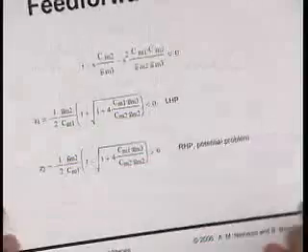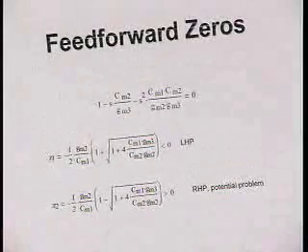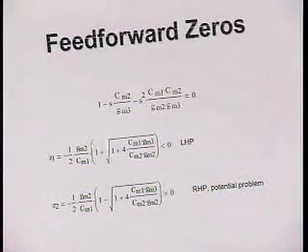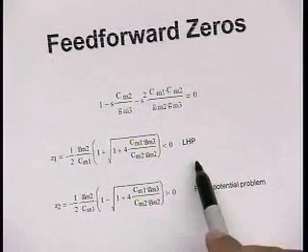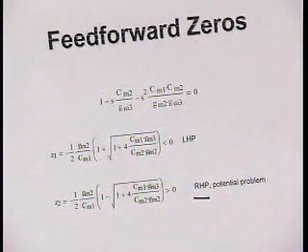One small wrinkle we have to deal with is the zeros. It turns out that you have a right half plane 0, right? Just as you would expect. We had it in a normal Miller. We're going to have it here as well. And we have to watch out for the 0, just like we did with the 0 from the two-stage design. Some of the tricks that we use for two-stage could also be used here, right?